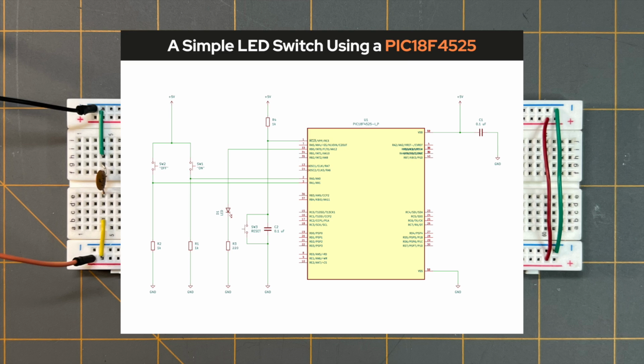VDD is used as the positive supply voltage. VSS is used as the negative supply voltage. Looking at our schematic, we see that we will connect both VDD pins together to the plus 5 volt supply. From this connection is a 0.1 microfarad ceramic capacitor in parallel to it and ground.